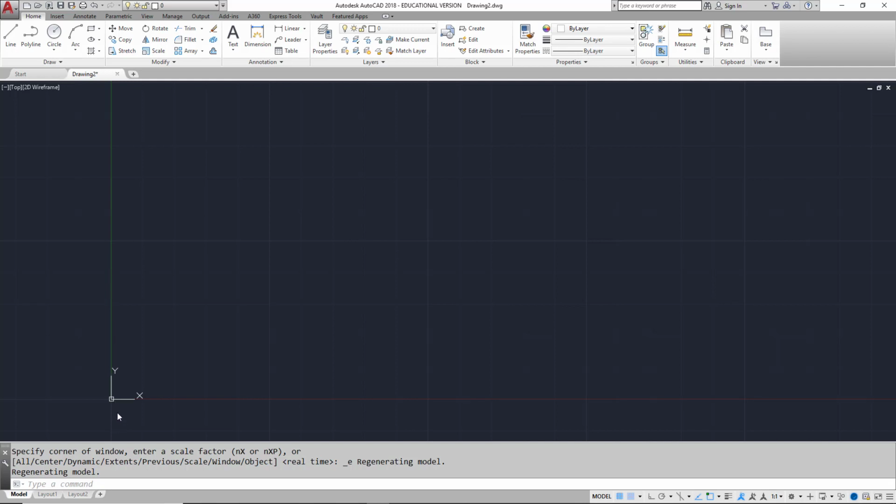When you enter coordinate values, you indicate a point's location along the x and y axes relative to the coordinate system origin, or 0, 0. In two-dimensional drawings, you specify the points on the xy plane, also known as the work plane. The work plane is similar to a flat sheet of grid paper. The x value of a Cartesian coordinate specifies a horizontal distance, and the y value specifies a vertical distance. The origin point 0, 0 indicates where those two axes intersect.